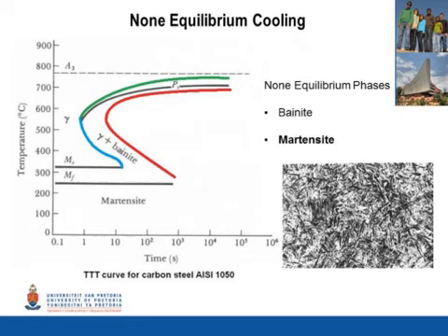The green line signals the start of the pearlite transformation at slower cooling rates. At higher cooling rates, the material may transform to bainite. The bainite transformation is shown by the blue line. At very high cooling rates, it is possible to form martensite. The martensite transformation start occurs along the black line labeled MS. Transformations are complete and no other transformations take place past the red line, or the line labeled MF.